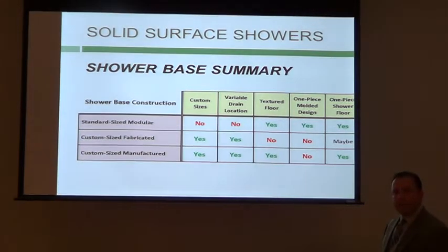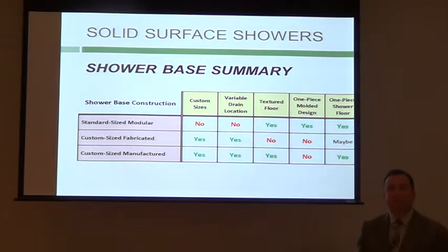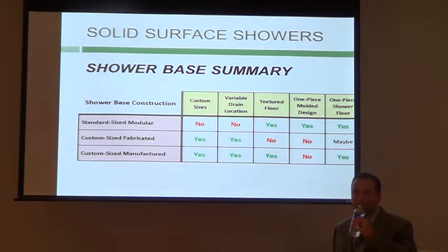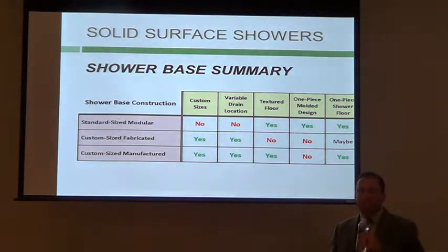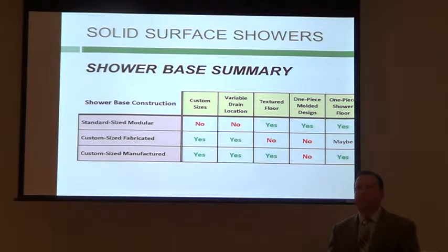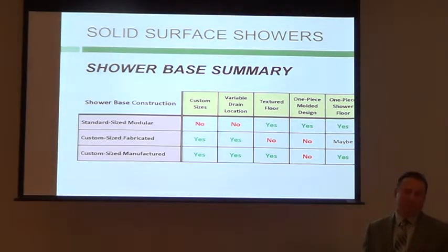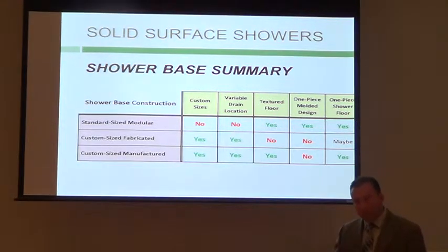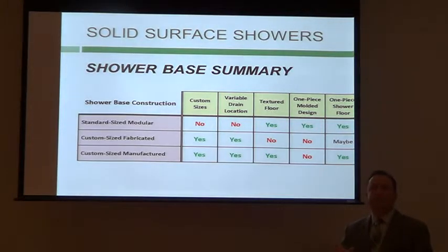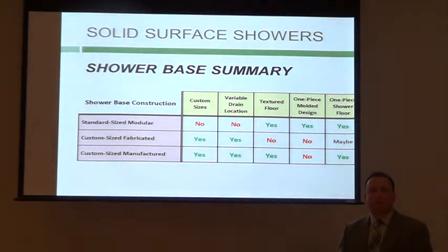Any questions on that? Yes? What's the static load limit then of the 1/2 inch fabricated base? The load? Yeah, the load. That's a great question. If that's 2,500, you said, right? The data exists. I don't know it off the top of my head. There's a deflection rating that I think if you apply 200 pounds, it can't deflect more than like 1/8 of an inch or something like that. But in a shower base, you're actually putting it onto a firm substrate, so that's not really applicable. So you're almost looking at a load test compression strength. Every manufacturer has that in a PSI rating, I think. So it is available.